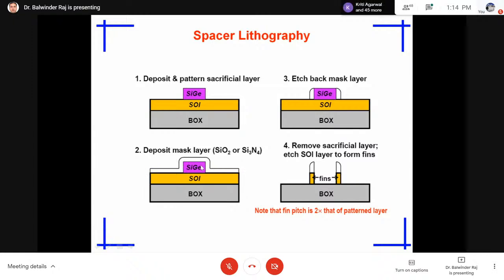After etching, we have to remove the unwanted material, and only above this gate we require this. How can we do this? By applying the mask. After applying the mask, we have to apply from external UV light or some chemicals or bias voltage to remove the unwanted material. So with this, this is the final structure.